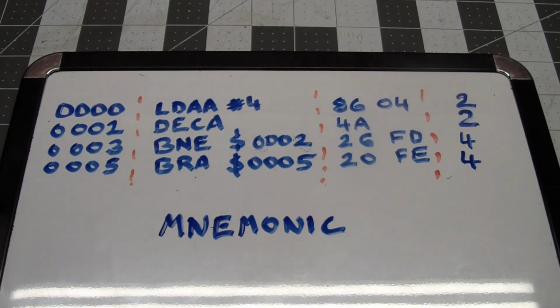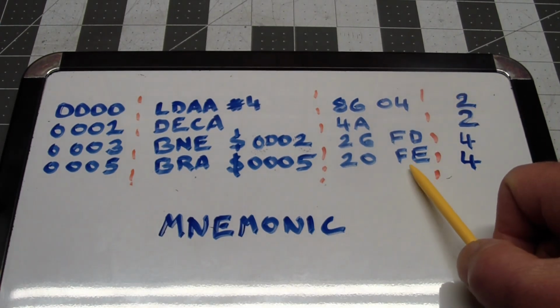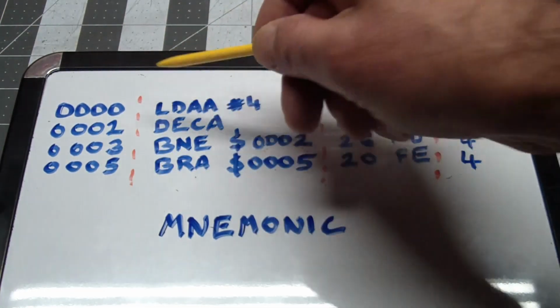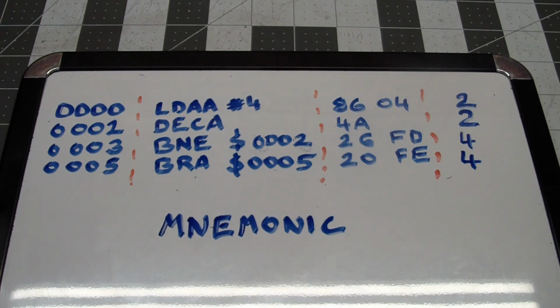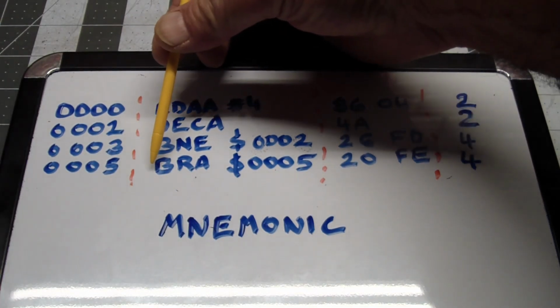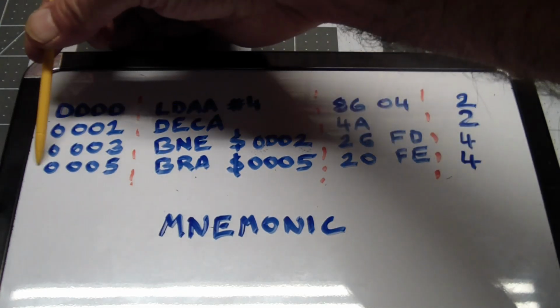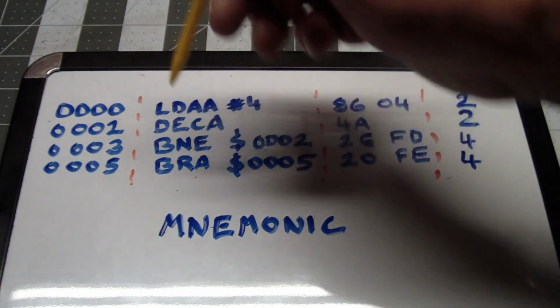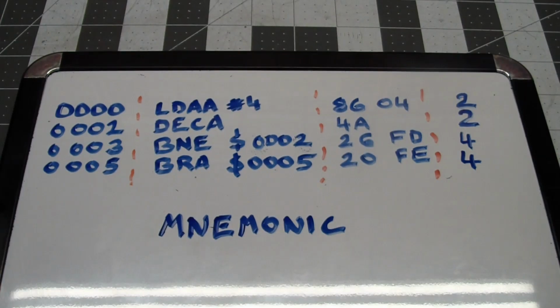Now in a branch, you don't get something for nothing. You still have a byte operand, which limits how far you can actually jump in the address space. Well, a byte has one of 256 different values. But suffice it to say that when you're using a 2's complement, and I may be slightly off in that, I think the branch can specify from the actual branch address a distance of -128 up to a distance of +127.